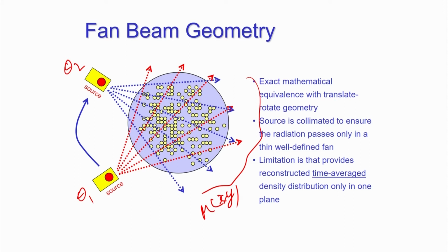But the good point in gamma ray densitometry or tomography is that the spatial resolution is very good. That depends on how much you move, how close you want. If you want to make a device which is very accurate, you can move the detector and source together by as little as 0.1 mm, 0.2 mm, 0.5 mm or 1 mm, whatever you want. That is the major advantage of this technique: the spatial resolution is very high, while the temporal resolution is not very high.